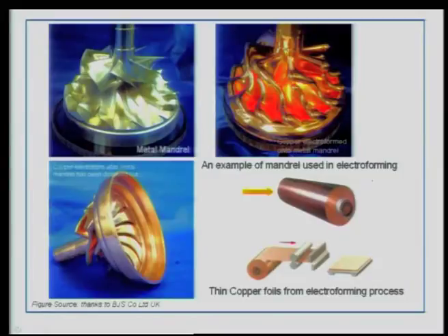If you are going to mill every part like this, it is going to take a lot of time. So, the best solution is electroforming. So, if you make a mandrel for a structure which finally should be this. Okay. So, this is a mold-like structure you make out of aluminum, for example, in this case, which this company has done. Then plating is done on this mandrel. This figure shows that complete electroplating has been done using the electroforming process onto the metal mandrel.